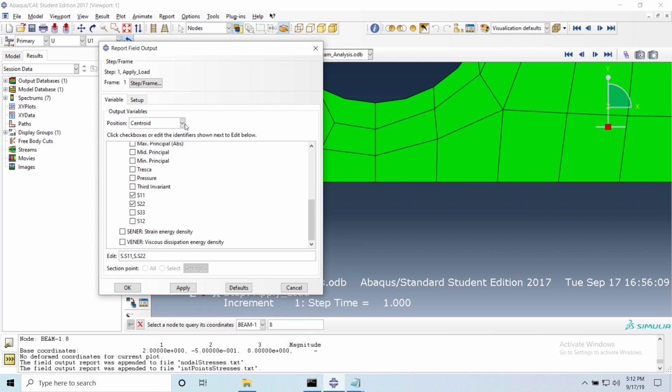When you have stresses at a node, it's because you did a weighted solution in order to extrapolate to the node. So stresses and strains are at the integration points, but displacements are computed at the nodes. You don't get displacements at the integration points. Stresses inside the element, and nodes have displacements. You have stresses at the nodes, but they're extrapolated from whatever you got inside.